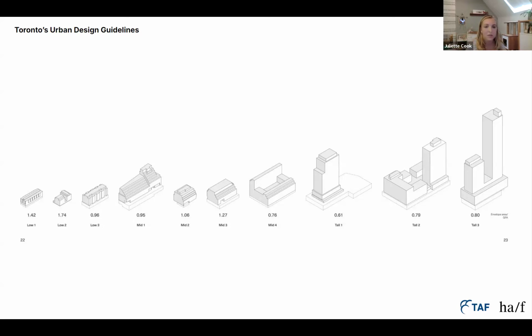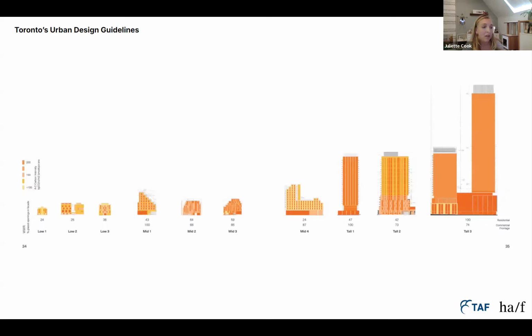And so we worked through various ways of visualizing and understanding the different embodied carbon results that you can read in the very wonderful study that came out of this project at more length. One drawing I'll call out specifically is this heat map where we looked at the impact of the different facade areas, in terms of their carbon intensive nature. The darker orange represents ones that are higher carbon and the lighter colors, the lower carbon assemblies.